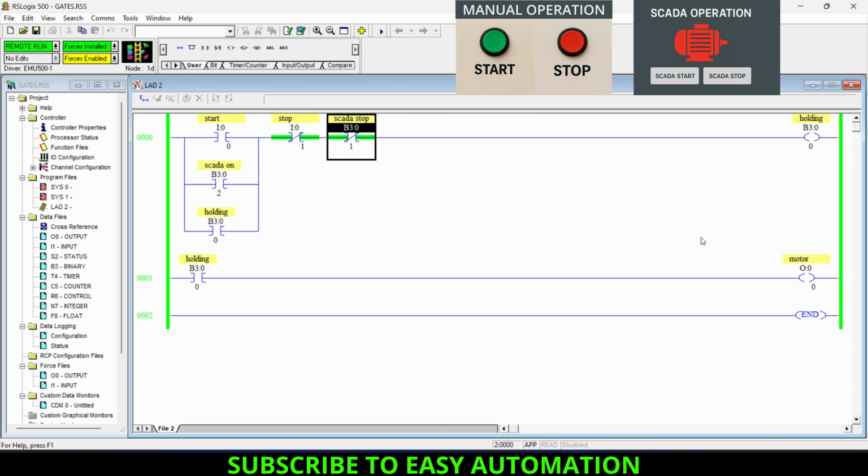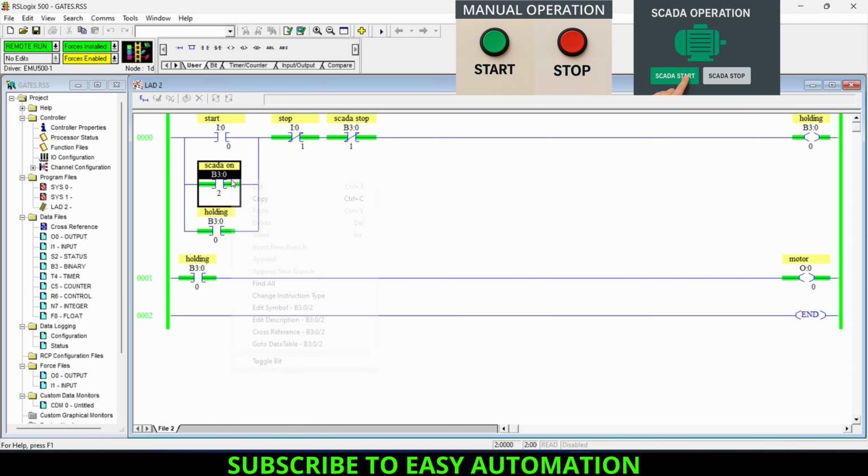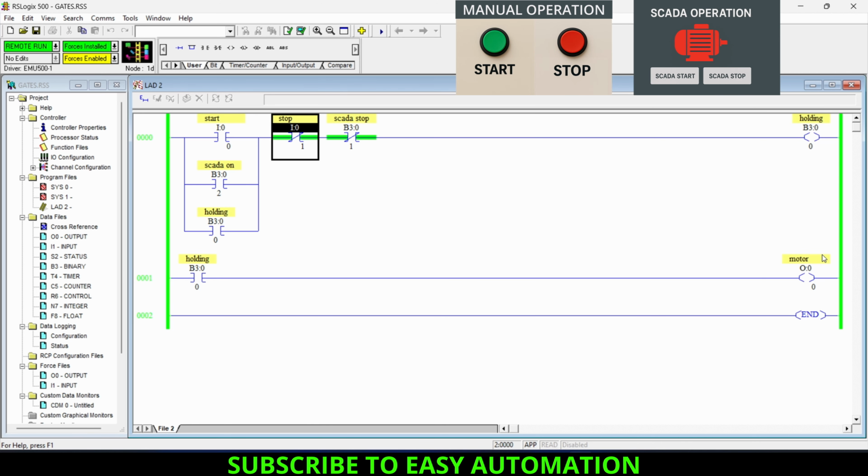And if I want to turn on this motor from SCADA, the operator will toggle this bit high and our motor will start, and whenever he releases his finger from the screen, the bit will go off, but our motor is still on because I have used one holding here. And if the operator wants to turn off this motor from the stop push button, he will push this stop button and release it, then our motor will get stopped here.